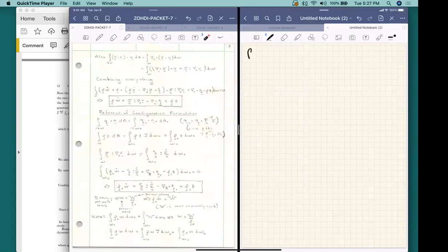And it's important to write it out. It looks like the integral over omega of rho w dot. So again, this is the density, and this is the important part that you need to focus on. That's the density. This is the stored energy in the body. So its time derivative, plus the velocity of every point in the body times the density times the velocity's derivative with respect to time,